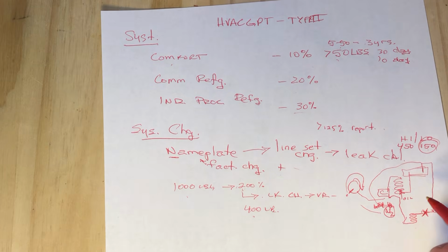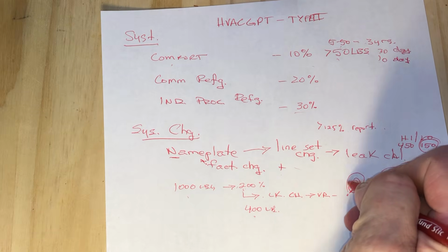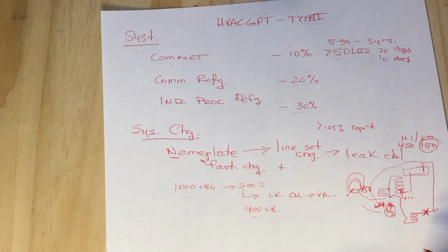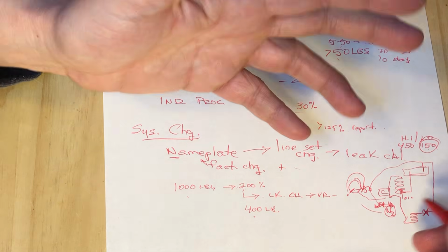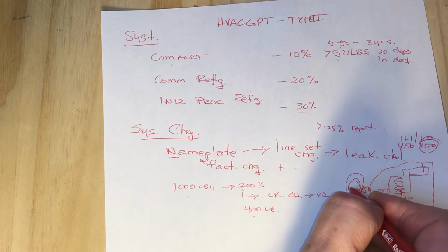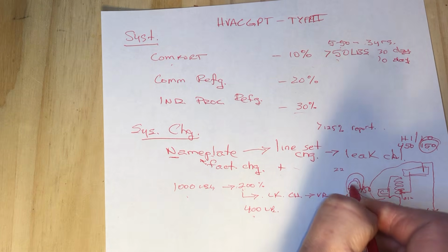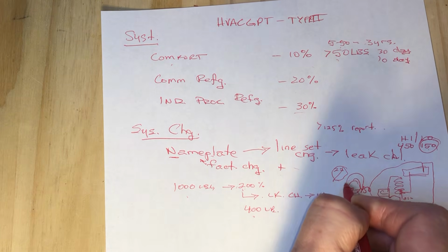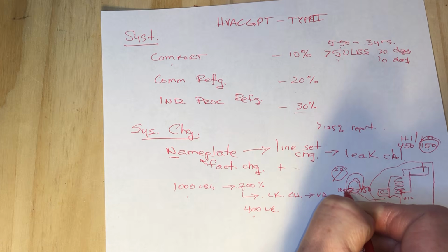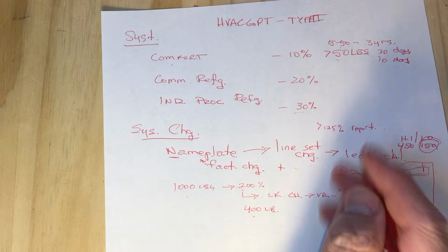But whatever the 150 is, let's say you push this up to 150 psi and the needle drops down, that means you still have a leak. The verification test failed, and let's say you can't find it, you can't hear it, you don't see a trace of oil. Then you might want to add a little bit of trace gas. Back at the nameplate, it tells you whatever refrigerant it is. Let's say it's R22. That's what you put as a tank for about 10 psi of trace gas before you put the 150 psi of nitrogen pressure behind it to raise it up to a test pressure range. And then you can just vent that out into the atmosphere.